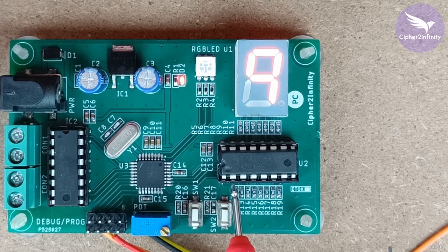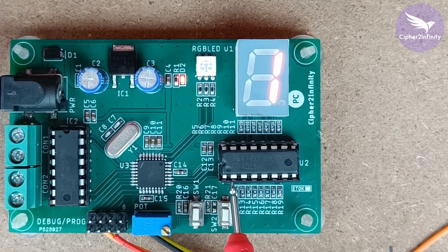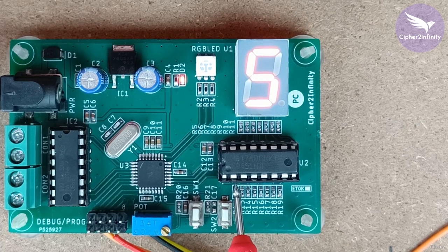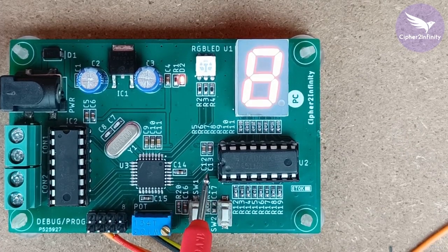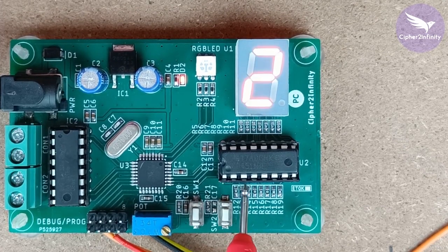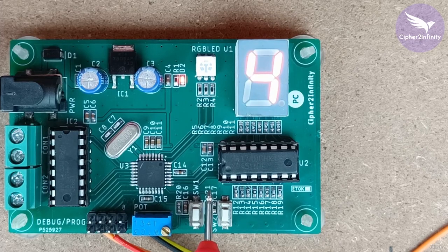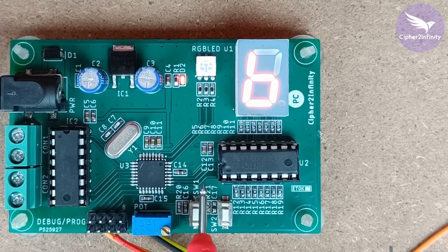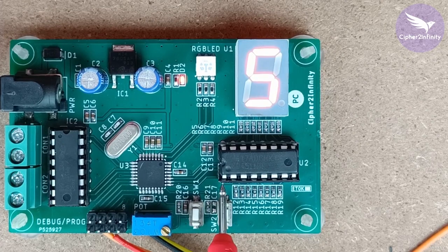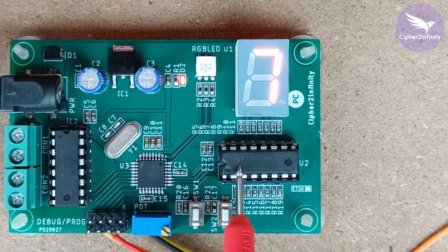So always make sure that while soldering the IC base on the PCB, you are soldering it in the right orientation. That's why we provide the silk screen on the PCB, so that you can insert the IC base in the right orientation. On the silk screen there will always be a notch for the through-hole IC. So that's the second point, which is related to the orientation of the IC base.